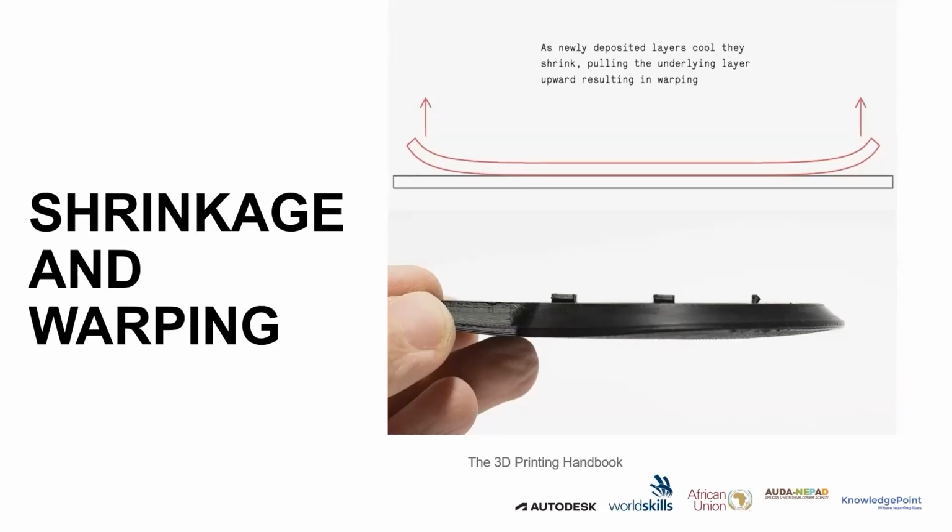And we're also going to talk about how we can mitigate warpage and all that. But as one area of the print cools, let me repeat, it contracts. This contraction leads to shrinkage of the build material. The contraction also pulls the surrounding areas, creating internal stresses. This is why filaments that print at 200 to 230 degrees require enclosed volume and heated beds.